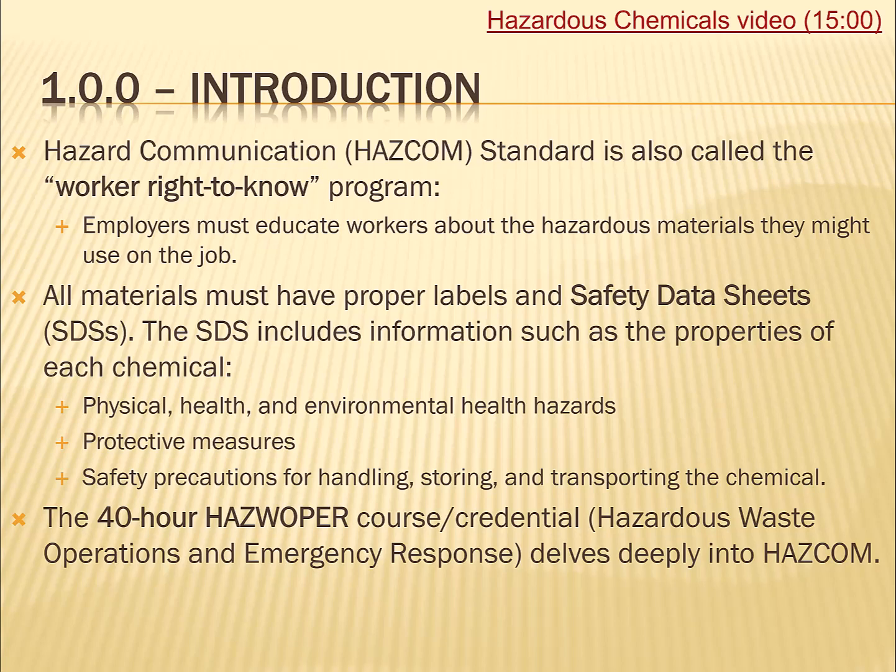The SDS includes information such as the properties of each chemical, like the physical, health, and environmental hazards, protective measures about how you protect yourself, that means personal protective equipment, and techniques of how you deal with spills, fires, contact, and that sort of thing, and first aid measures. There are safety precautions for the handling, storage, and transportation of the chemical.